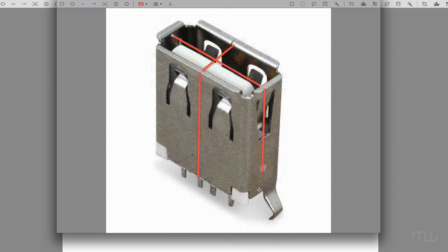Now, this bottom section here and these details, they're not symmetrical front to back, but they are symmetrical kind of left to right. So we could think of this area here being a separate issue here, where it's only symmetrical on this side and this side. So the plan here would be to create a cube, split it up into quarters, model all of this detail here, put it into double symmetry, and then join this area back up and just use single symmetry between these two sides.